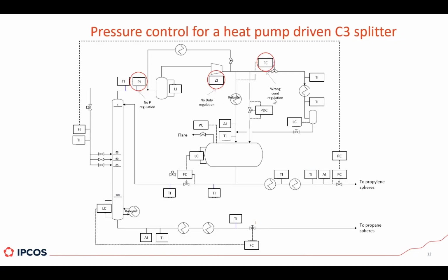Let's quickly go back. I don't know if any of you noticed that part of the vapors actually go through a separate condenser. So not all of the vapors can be condensed in the reboiler. A part of them are actually condensed in a little condenser that uses cooling water.